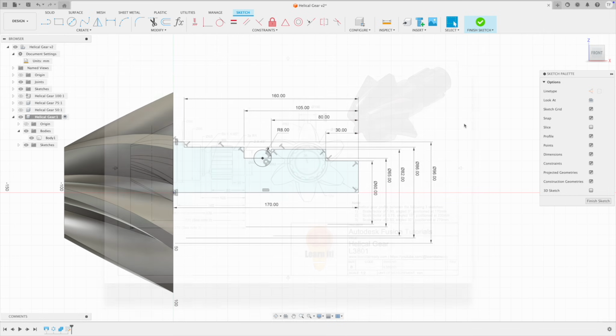The reason is sometimes it's very easy to forget a dimension even though you've highlighted it. And in the manufacturing world, if you forget a dimension and you run 1,000 pieces, 10,000 pieces, 50,000 pieces, and then you realize at the end you've missed a dimension, well, whose fault is that going to be? So I double check. Measure twice, cut once is the principle, and that's what I end up doing.